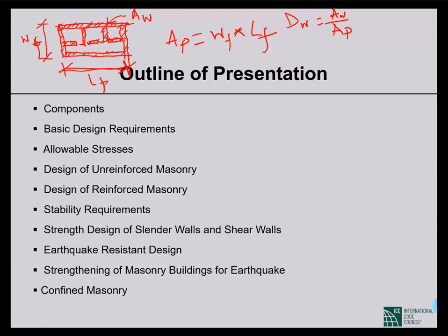There are some guidelines regarding that. In the foundation chapter, you have all the necessary information regarding strip foundation. Basically, masonry foundation will be strip foundation, and all the relevant information regarding that is given in part 6, chapter 3.